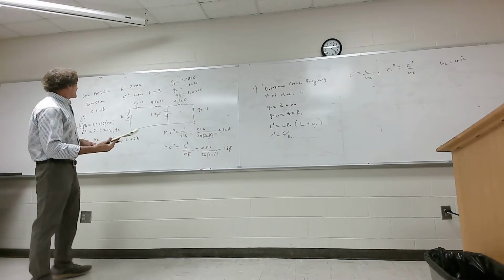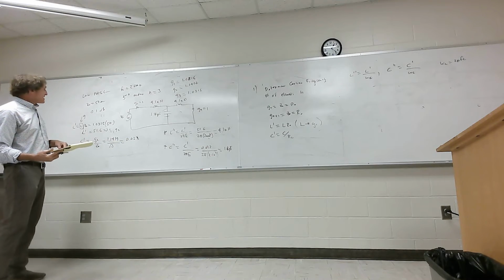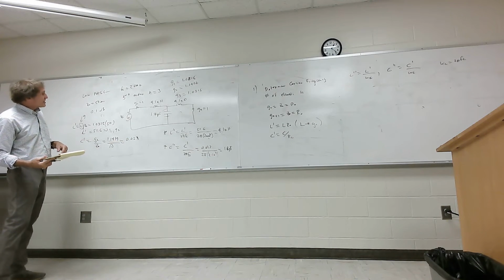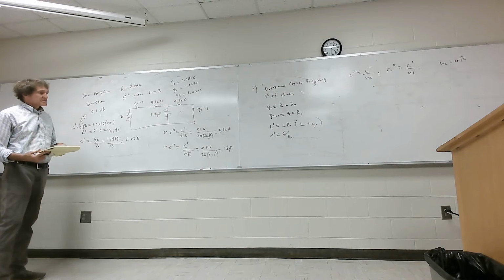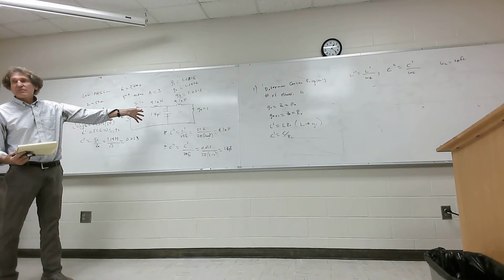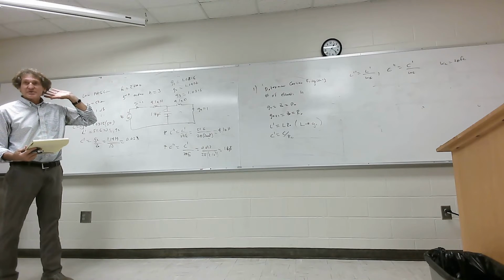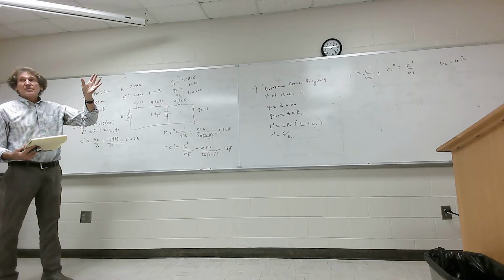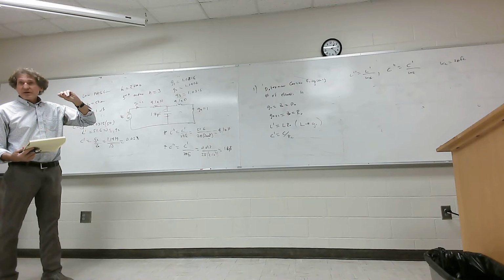We would get 0.1 dB of ripple, and we have a cutoff frequency of 2 gigahertz. Now, I'm going to ask you one thing. As far as the order of roll-off, what do you think it would be for that one? For a single capacitor added, do you all remember the actual dB roll-off is 20 dB per decade? Do you all remember that?